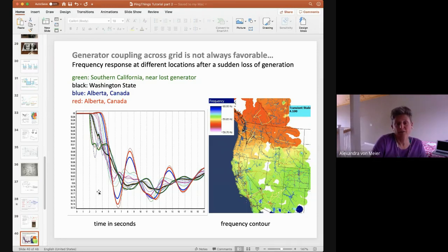And then there's the big question of, as we begin to replace rotating machines with inverters, will the inverters make this better or worse? And the answer is, well, we don't really know, and it'll depend on how we control the inverters. But how do we validate that we are controlling inverters intelligently? We need grid data measurements, and specifically PMU measurements for that.